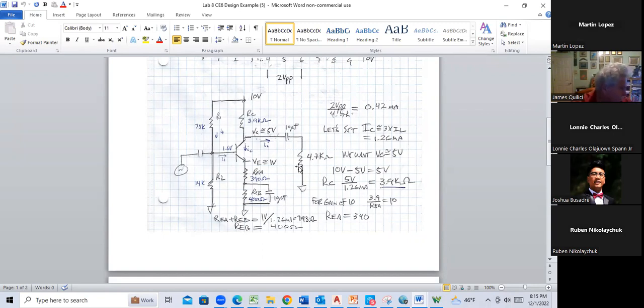Looks like I have in my little resistor kit here, this isn't the one with the Analog Discovery, this is another one I have, I've got 120 ohms and I've got 150 ohms. I'll put in 150 and see if I can get my gain up to 10. Okay, let me swap that in real quick.